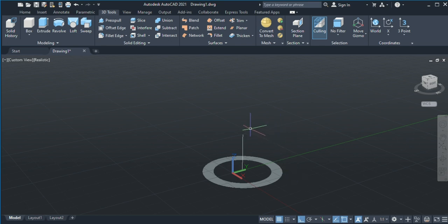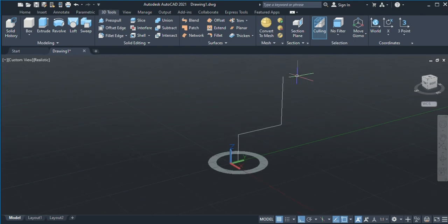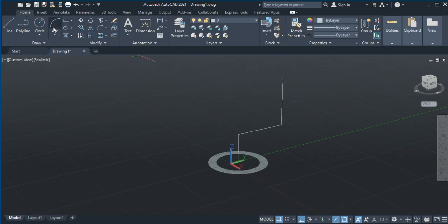You can do arc with radius, but you want to make sure everything is easier. Here you can see it's 260, so it's actually a quarter of a circle with a radius of 260. I can also just do 260 and then 260, right? So then what you need to do is an arc.